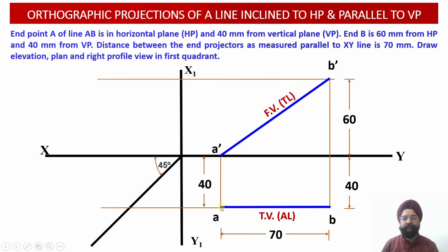So how can this be obtained? We have to draw a horizontal projector line through the point A in the plan and extend this projector line till it intersects with this transfer line at this position. Wherever we get this point of intersection, we have obtained a point on the transfer line corresponding to this plan projection line.